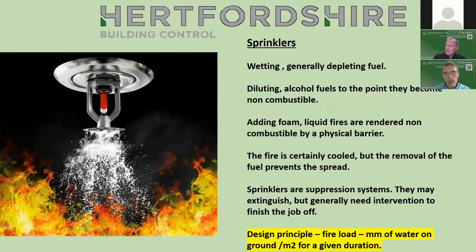reduce the heat. Certain sprinkler systems can add foam. Liquid fires are extinguished on the basis of the physical barrier that the foam creates between the combustible volatile gases and the atmosphere. So that's basically how the foam tends to work. The fire is certainly cooled, but the removal of the fuel prevents the spread.